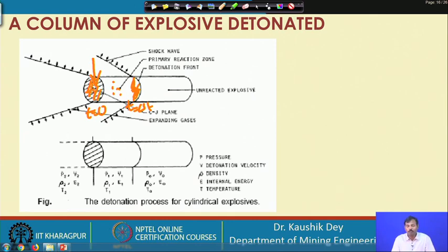So, now from this lecture we understand that the explosive on detonation is immediately disintegrated into the elements, releasing the shock that starts travelling in all directions. Then it takes some time to form the gaseous products, and that means the release of gas from explosive detonation lags a little behind the release of shock.